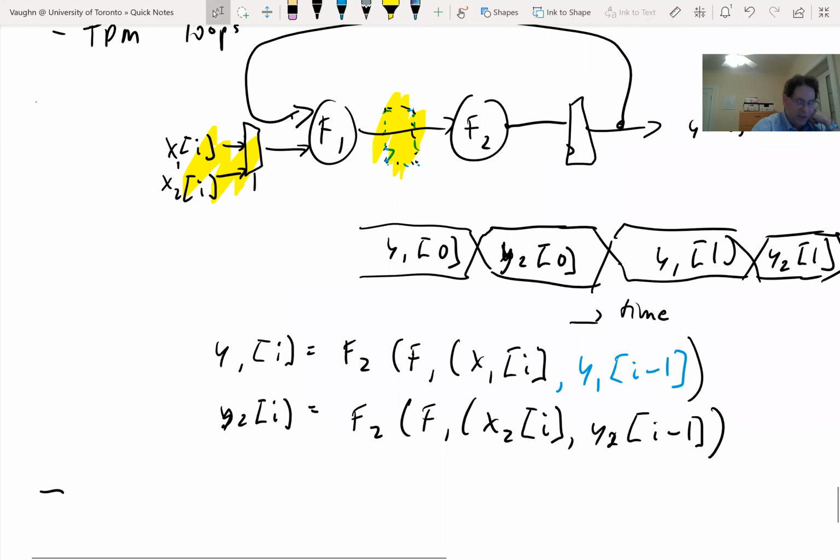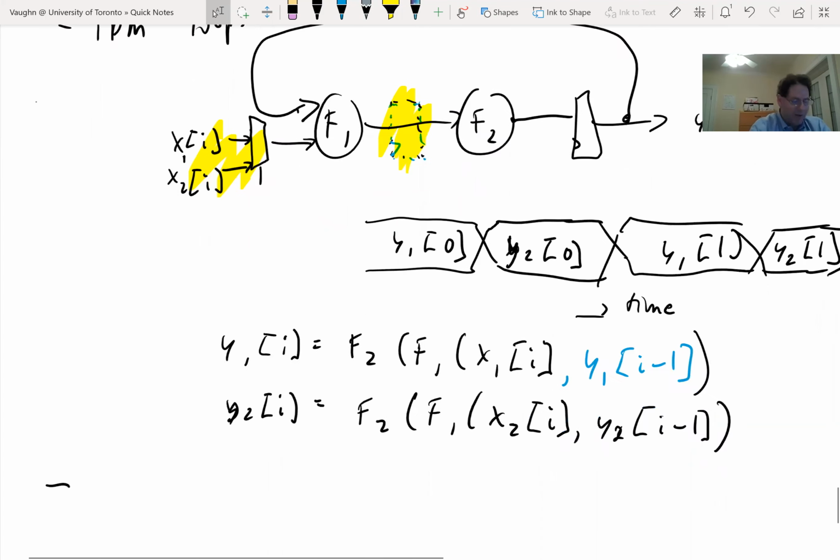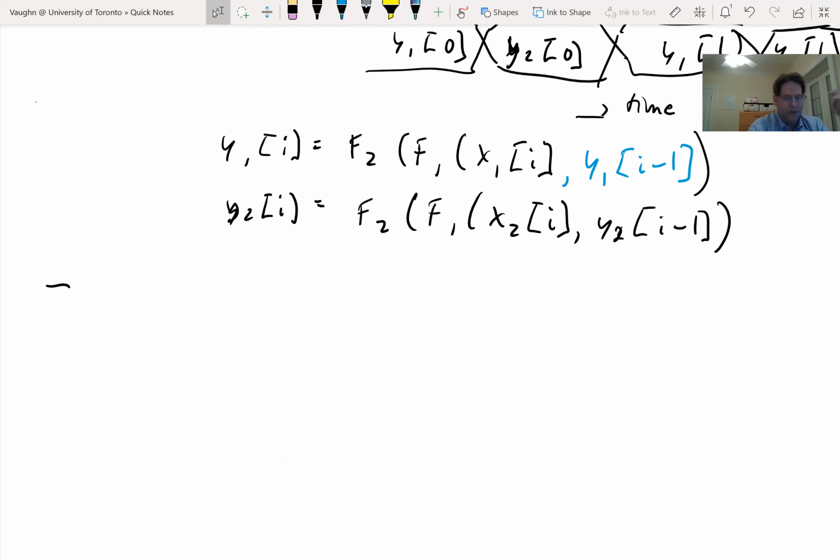So in this particular case where I've got a loop like this, and I'm going to interleave 2 streams, I have to do the pipelining at the same time, because interleaving 2 streams in a loop like this is actually going to break my behavior. Doubling the latency around the loop corrects that. So the 2 optimizations, the 2 changes together cancel out. But if I did one or the other alone, it would not be correct. So I have to do them together. So that's a good question.